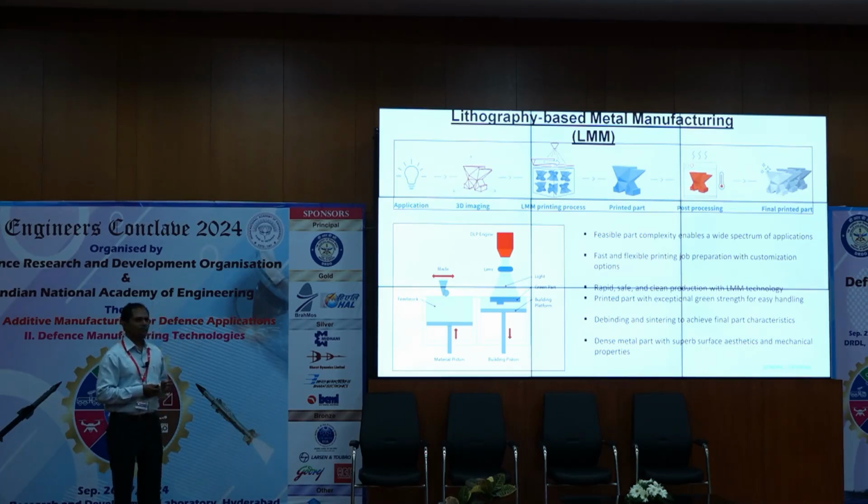Main advantage is getting very fine features. We can get micro featured components with this technology. This technology is very simple. You have a starting feedstock, which is mixed metal powder mixed with the photopolymer, and this feedstock is normally